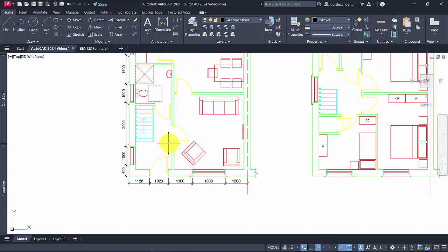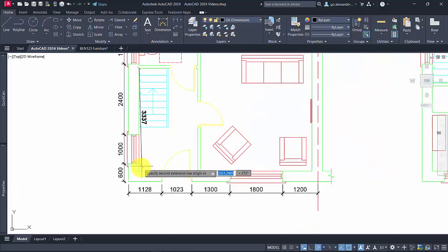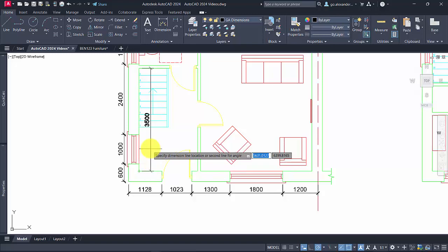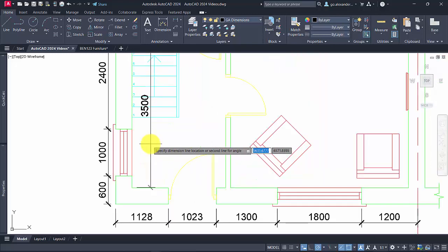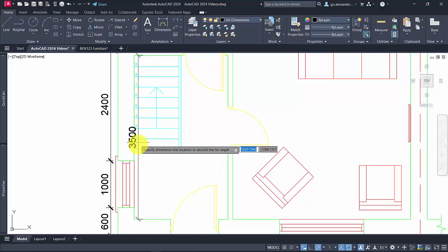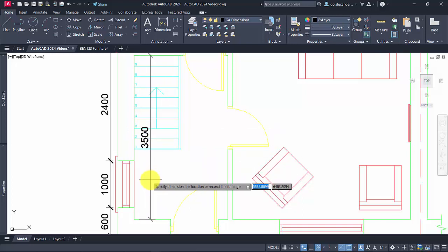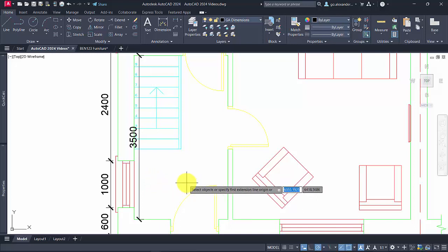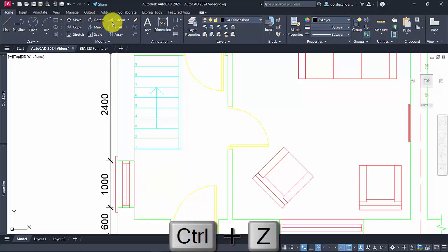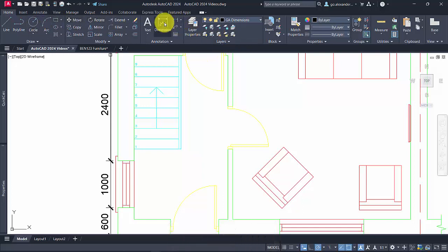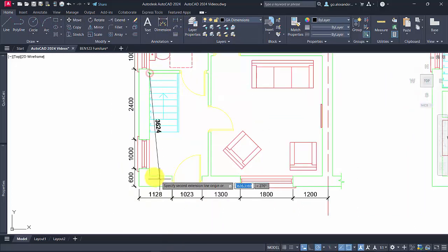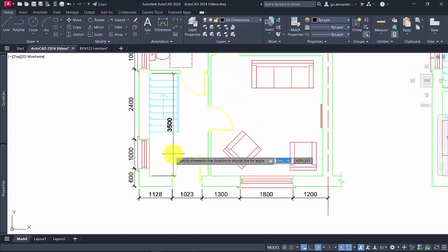Internally then, let's do a few examples. So let's see, we'll draw a dimension from here down to here. And with this, you do need to be careful where you place it. We don't really want to interfere with the numbers of the stairs, and we don't want to overlap it with the arrow that shows the direction up the stairs. So let's try a distance of 250 there. That seems about right. That didn't work. Let's try again. So it does take a little bit of care sometimes just with where you want to place the dimensions.